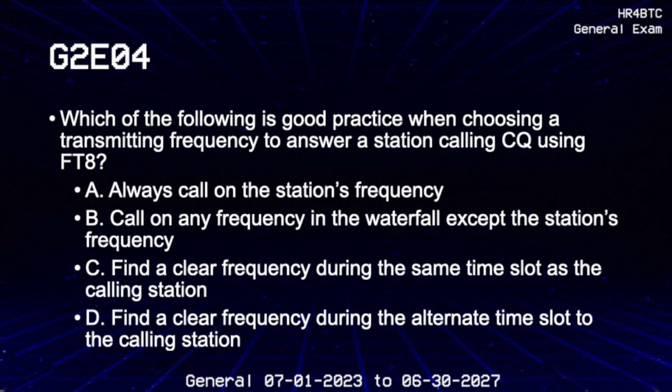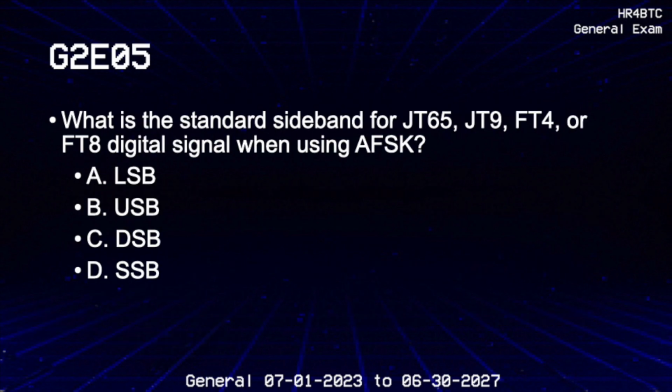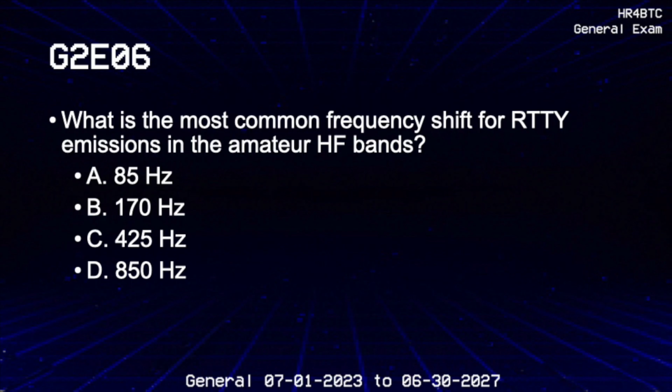Which of the following is good practice when choosing a transmitting frequency to answer a station calling CQ using FT8? Find a clear frequency during the alternate time slot to the calling station. What is the standard sideband for JT65, JT9, FT4, or FT8 digital signal when using AFSK? USB. What is the most common frequency shift for RTTY emissions in the amateur HF bands?